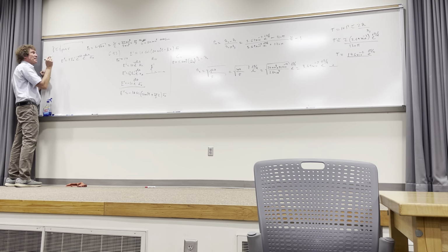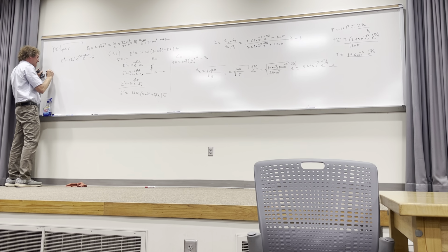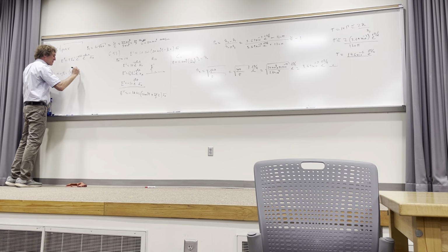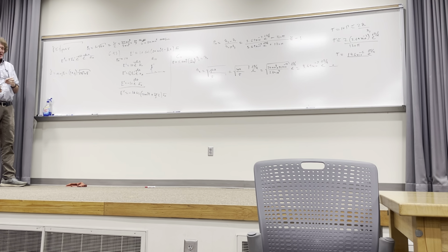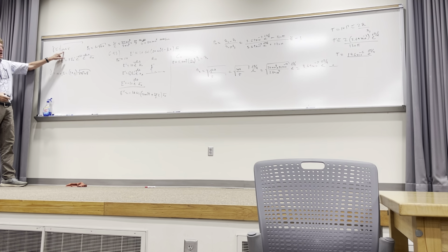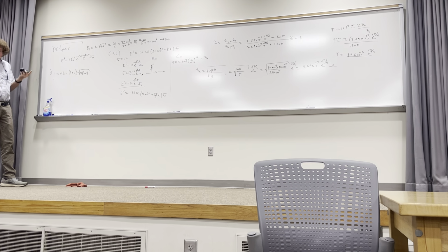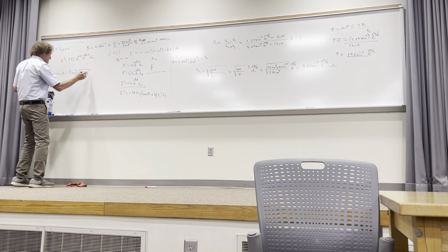For a good conductor, that means I would get gamma is equal to alpha plus j beta, and it would be simply 1 plus j times the square root of pi f mu sigma. Now, I've done a couple of things here. First, I know that omega is 2 pi f, okay? And I know when I get the square root of j, what I end up with is 1 plus j over the square root of 2. And if I mess with it a little, I get this. Do you all remember me doing that?